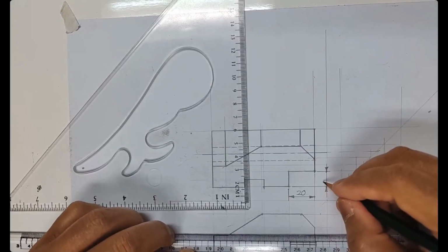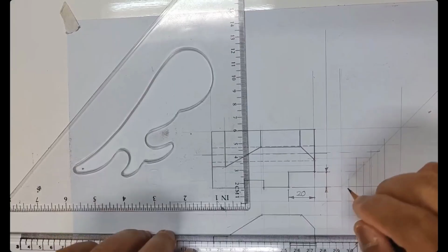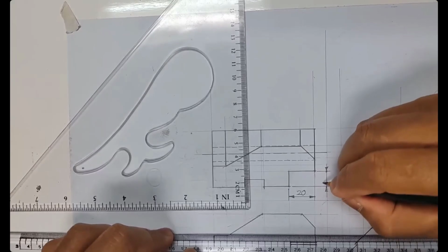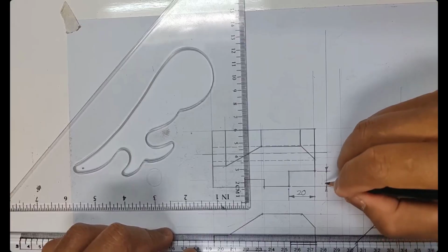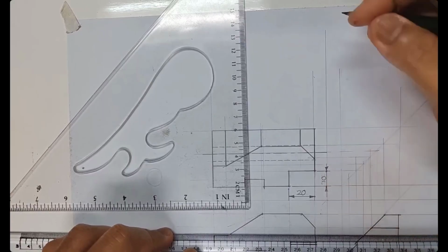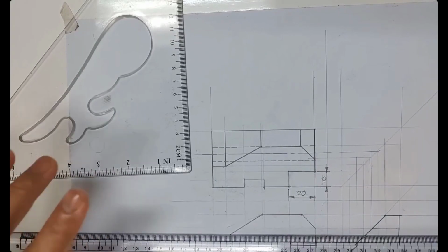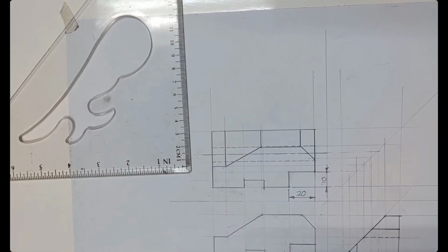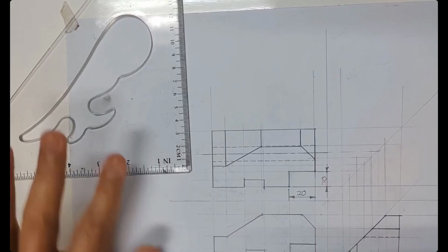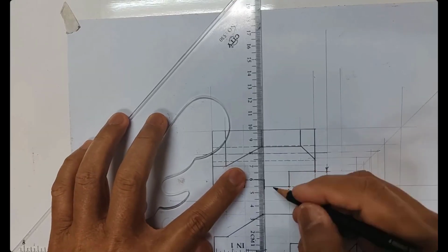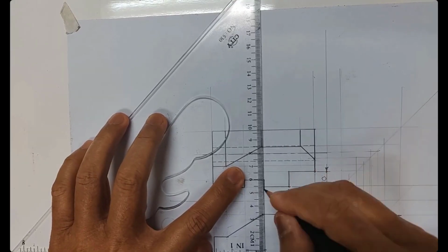So this one, okay, here the dimension is 10, right? The depth is 10. So you have to look on the right side. If your handwriting is terrible, you have to make a guideline of 3 millimeters, so this will be written properly. Okay, then you do the dimension of the rest, the 15. That only, okay, here because I think I have put a measurement of 20 already on the top view, and also here I have a 15. On the top view it clearly shows the profile. I can show clearly the features of the cut through.